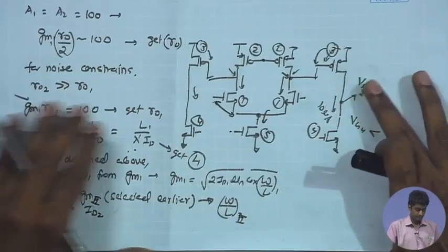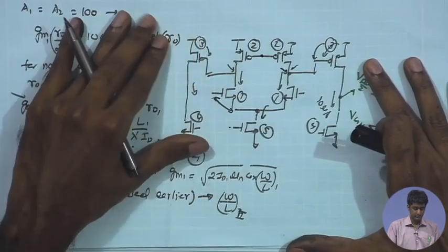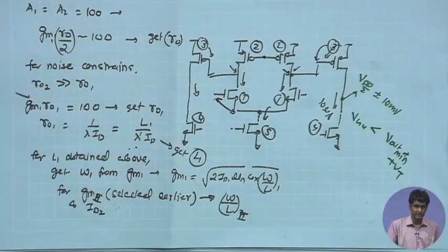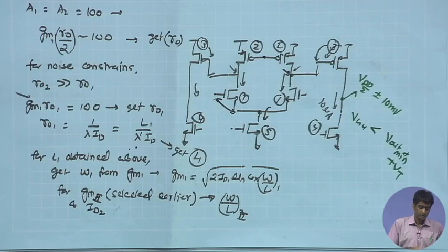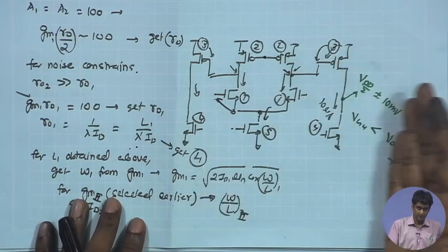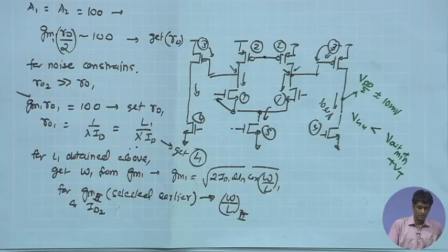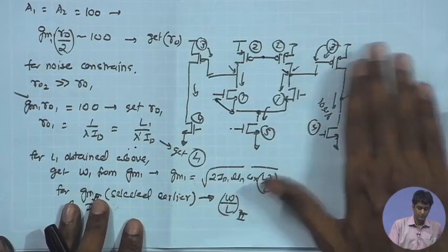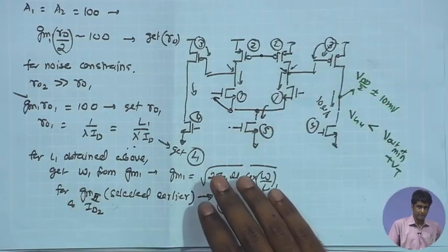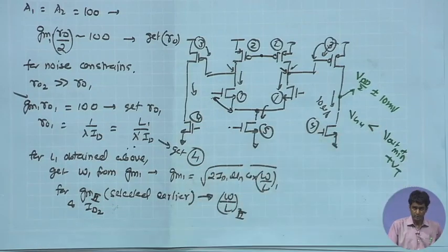Another issue that we have is the common mode feedback amplifier. There we have already studied that for the common mode feedback amplifier, if we are going for a single loop and we are using the diode connected load for the error amplifier, there of course the gain requirement is not so critical, and therefore the W by L and bias current can all be relatively lower, the sizing constraint can be relatively lower.